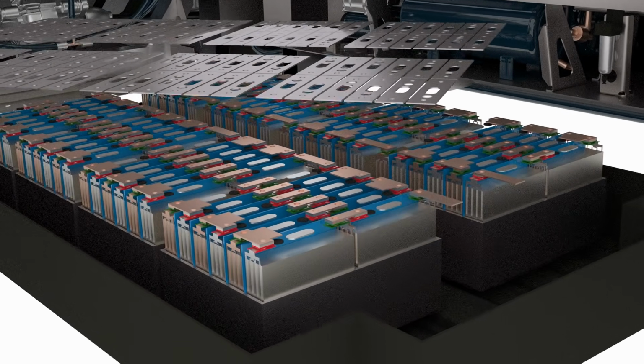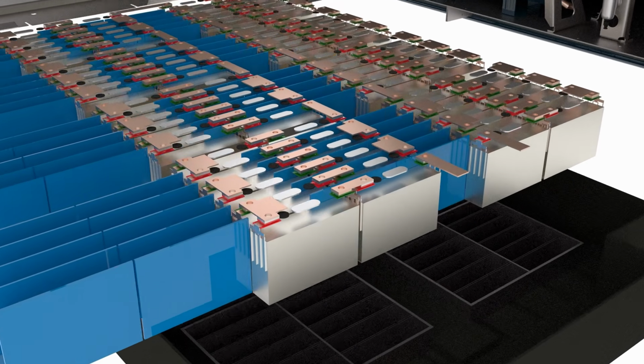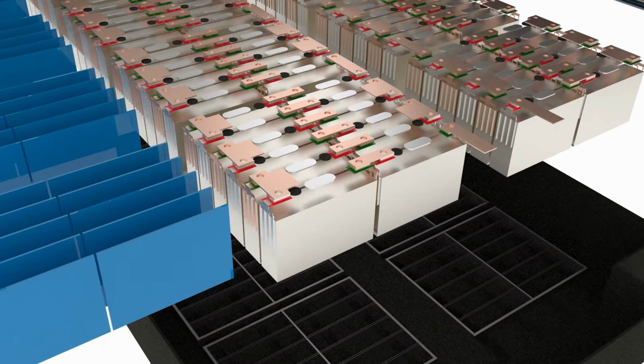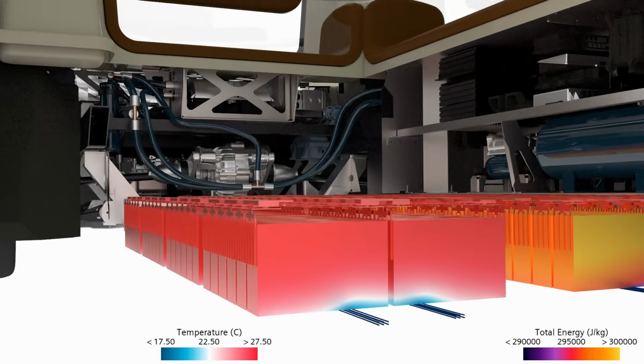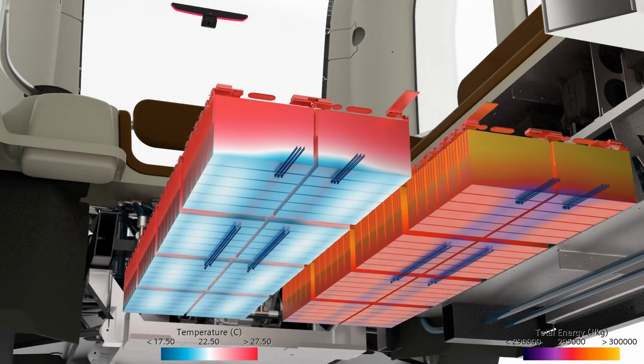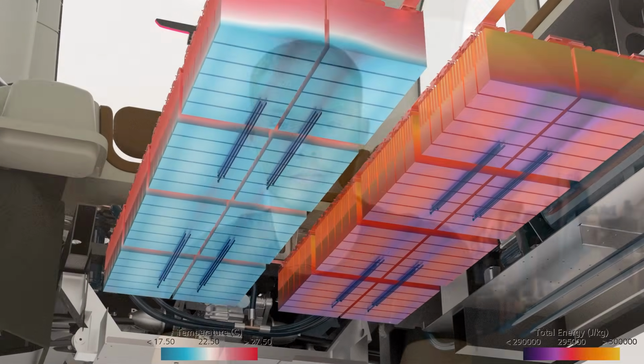A good example of that would maybe be something like the cooling of a battery pack, where the coolant channel is running on the fluid timescale. We can run that in steady state. Then we map to the solid, which runs transiently, and that mapping is done through the explicit mapped contact interface. So yeah, we really unlock a nice set of applications.